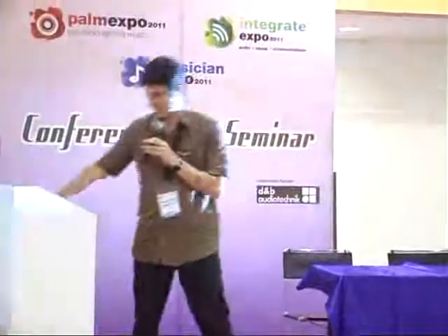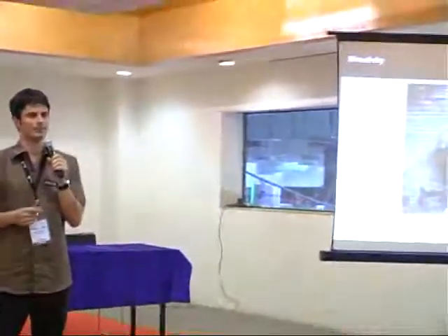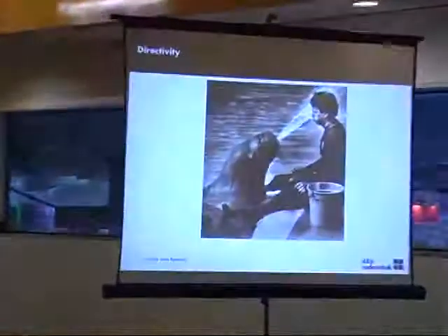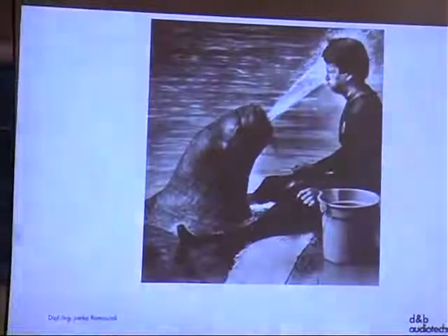Now, first question, why would we want directivity in low frequencies or any kind of frequency range in the first place? Well, especially when it comes to low frequencies, once you have a stage and you put a PA in front of that or next to that, you might have things on stage that don't react very well to low frequencies.